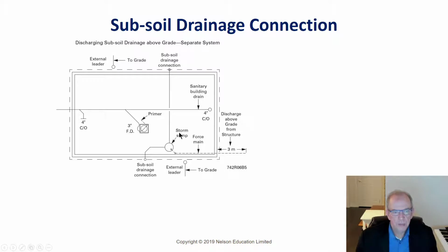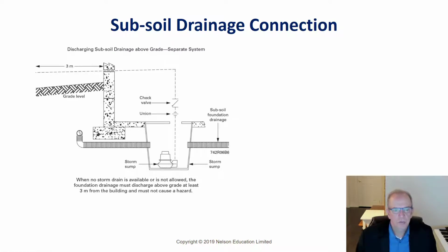And so this storm sump, which is a sump pump, is basically a hole that's put into the ground, and there's a container that goes around it, and into the container, which is open on the bottom, there's a pump. And as the water rises, as it's fed from the drainage tile around, then it's pumped out beyond the house. So it's basically looking something like this, and then this water is pumped out. A check valve just stops water from backing up as it was pumped out. So that's essentially how that works in that case.